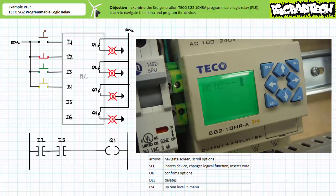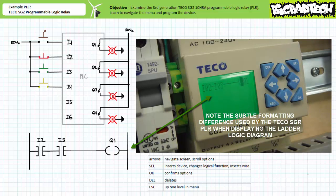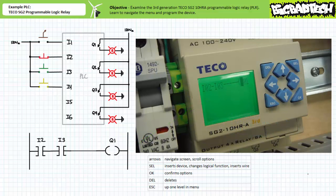Wiring is probably the most confusing part of programming any programmable logic controller using the front panel regardless of manufacturer. Again, if you dork something up, you can always delete it and try again. We're now in the coil field. Press Select to insert a coil. Note the device inserts the default output coil Q1. Luckily, this is the one we want. Press OK to select Q1. The device inserts a Q1 and moves us to the end of the first and only rung.